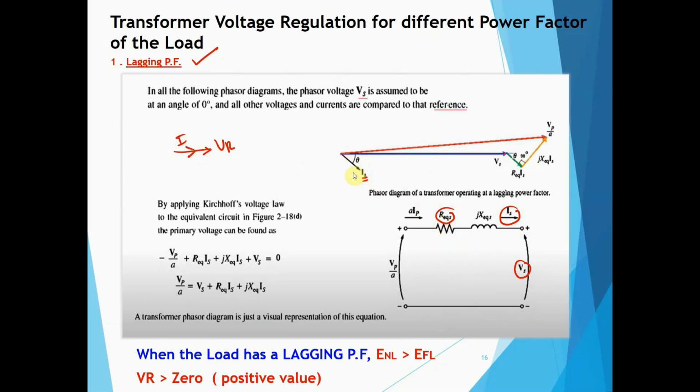Since this is a resistor, the phase of VR is the same. Since we are doing phasor addition, I can reflect this current phasor at this point here, where I can represent this voltage as VREQ, which is IS multiplied by REQ. Plus, if I take the KVL here, this voltage plus this voltage plus this voltage will be equal to this voltage, which is considered as the source.